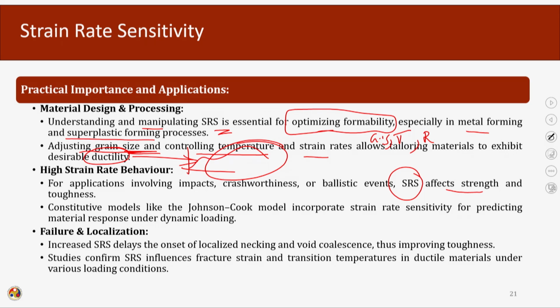We need to have a very good understanding of the constitutive models of the strain rate behavior, meaning we should be able to formulate this behavior in terms of equations, where the behavior is represented in the form of basic quantities. So, the stress is represented in terms of basic quantities like strain rate, modulus of the material, and so on and so forth.